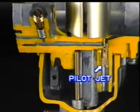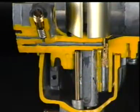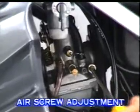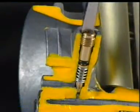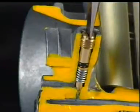The pilot jet measures the amount of fuel flowing to the engine during low-speed rotation. The volume of air coming in through the pilot air passage can be adjusted by the air screw. Tightening the screw narrows the passage and reduces the amount of air coming in, so that a richer air-fuel mixture is produced.